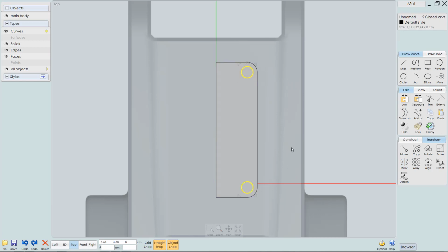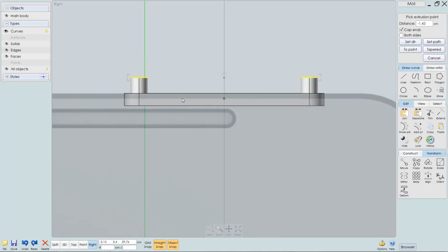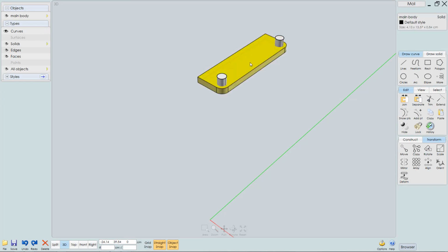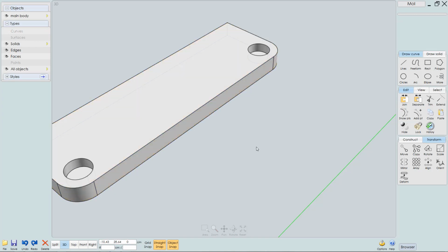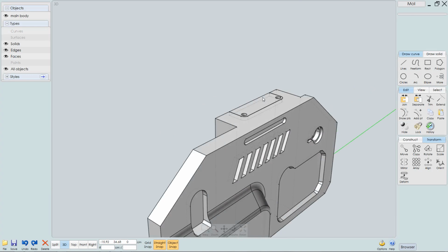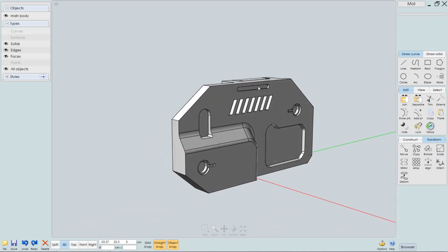Okay, select both of these objects, and I'll just move them straight up, extrude them down into that shape to maybe about here, and then do a Boolean Difference. Let's hit escape. Let's get rid of these curves first. So now I'm going to do a Boolean Difference. Hit Alt Q to unhide everything else, and there we go. And I think that's all the details that I want.